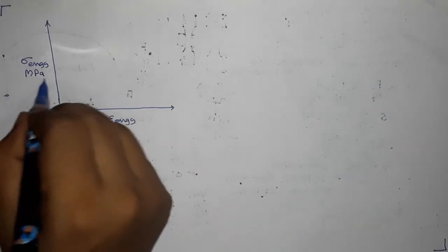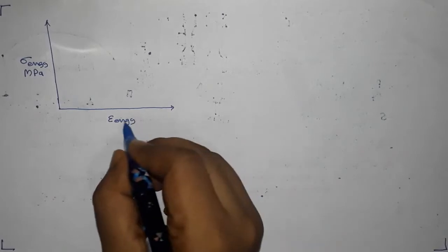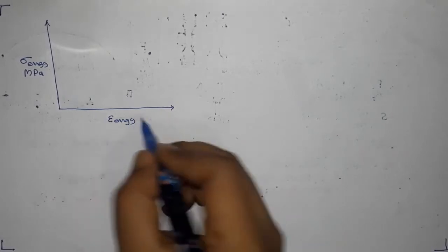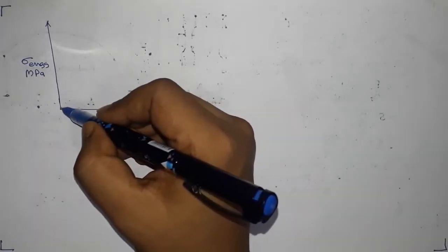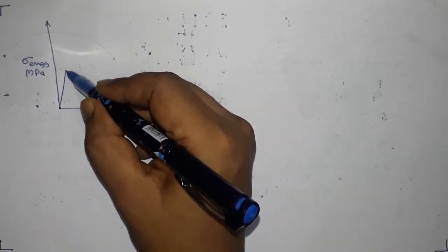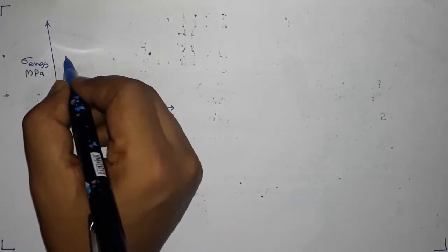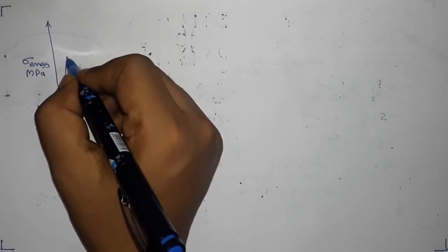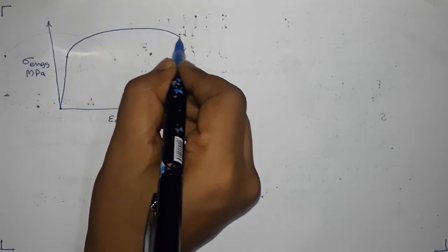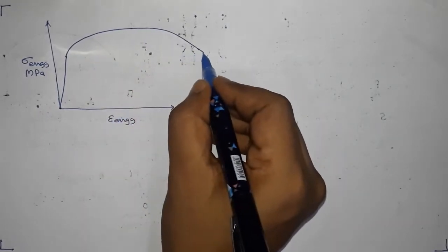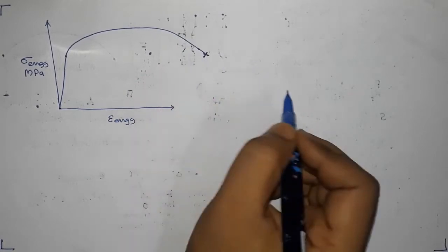So assuming that I have tested steel sample, and strain has no units, so this will be unitless. Okay, so this is engineering strain. So this graph will look something like this. So initially, and we'll talk about the different aspects of it, and then it will start non-linear and it will increase and then it will decrease and then it will fail. So at this point of time it failed, the specimen broke into two and the test stopped.